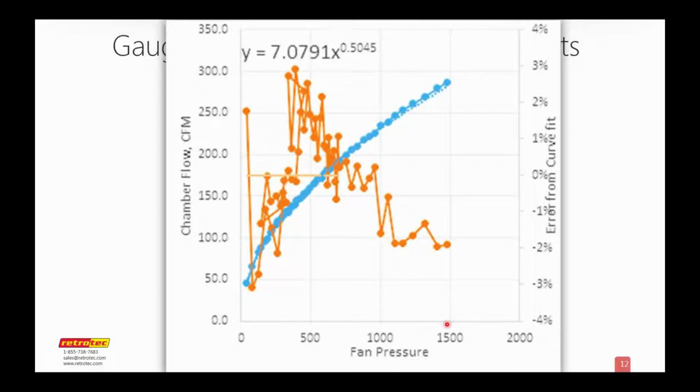This particular device is one that is used for testing commercial ducts, and it will actually go right up to 30 inches of water column, which is 7,500 pascals. It's a real monster in terms of how much pressure they can create. Very different from the small 25 pascal pressures that we use. And I thought it might be interesting for the people out there to see the extent that we go through to look at our devices and make sure that we understand exactly how they perform.